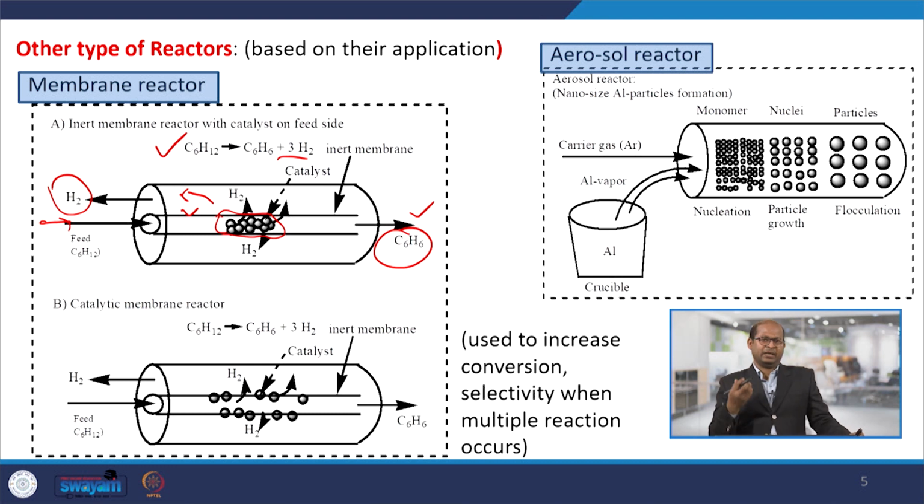Means that catalyst, if it is required, we can place as a bed inside of this type of reactor, or maybe with the membranes, when we prepare the membranes, the catalyst will also be placed with them. So, over the surface of the membranes, catalyst in the form of particles would be there, and when reactants pass through that catalyst or reactor, reactions will take place in the presence of catalyst. Similar catalytic operations and separations we can also conduct using this type of membrane reactor.